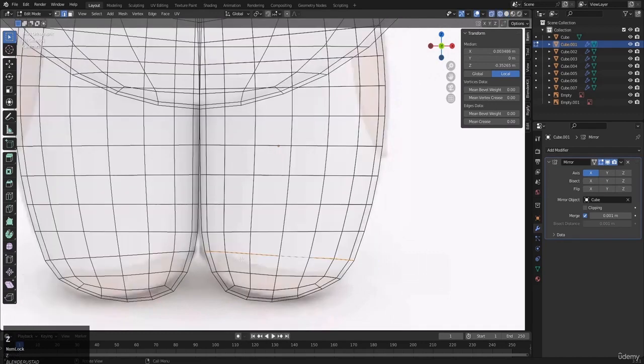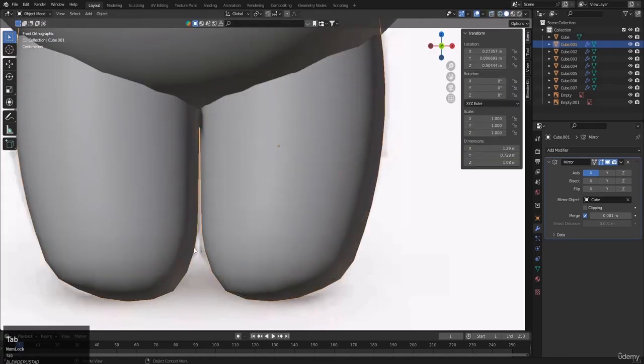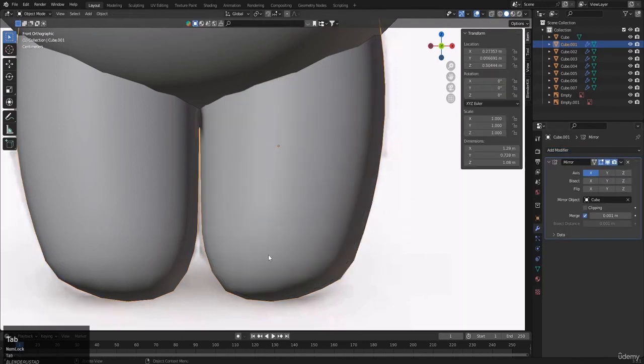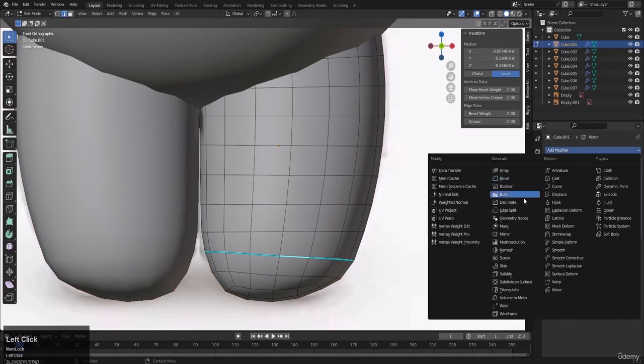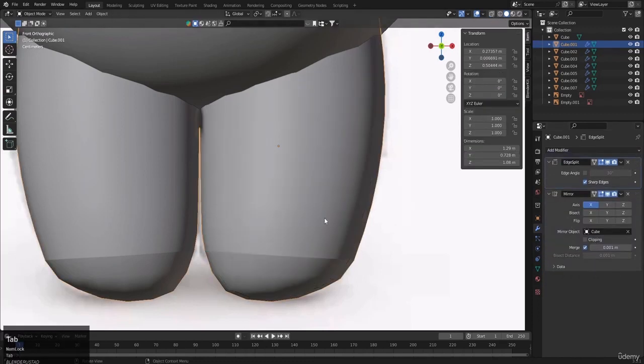Okay, so now select this loop, as we will consider the shape like this, and what we have to do is split the edge with the edge split modifier, but before that, Control E and mark sharp. So now we marked sharp and we can detect this with this modifier. So come up here and add an edge split modifier, and now just turn off this one. We only need the sharp edges to be split, and let's move this modifier to the top.